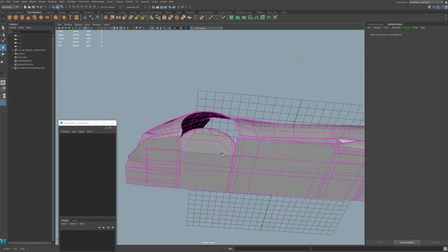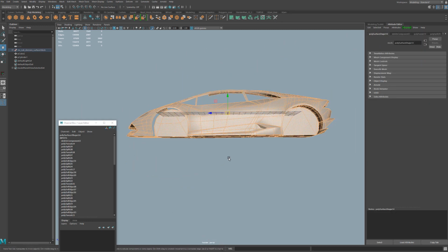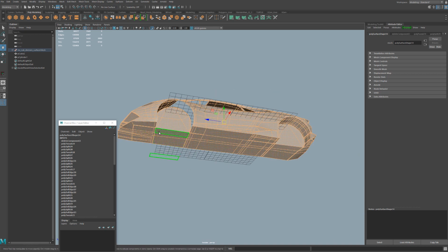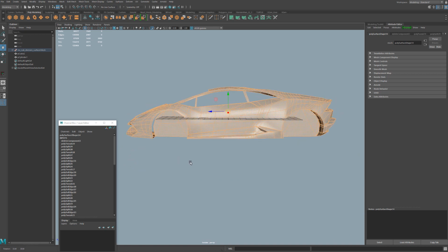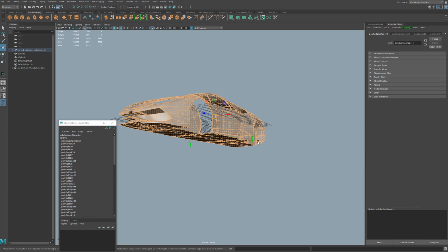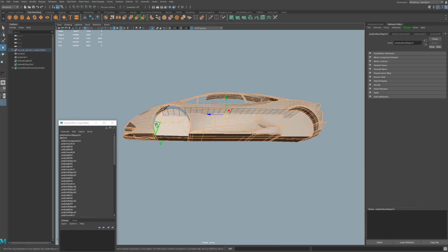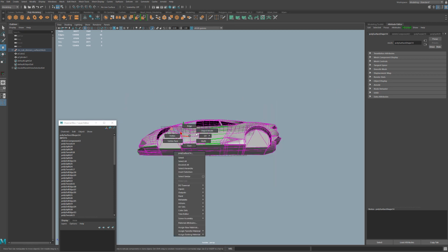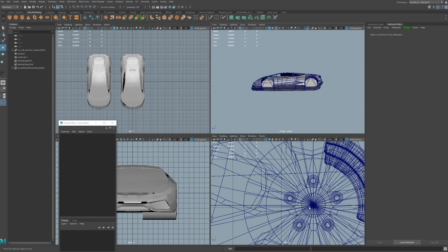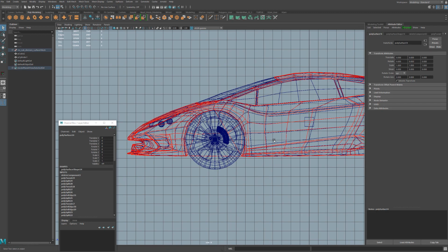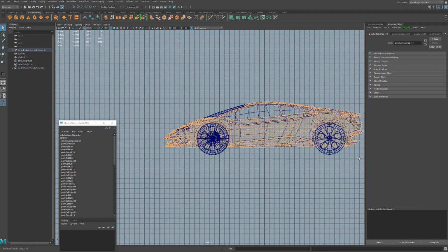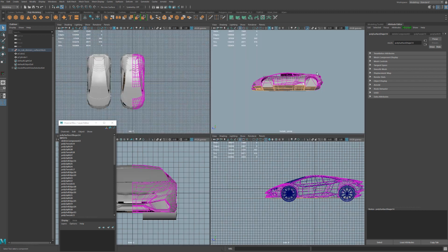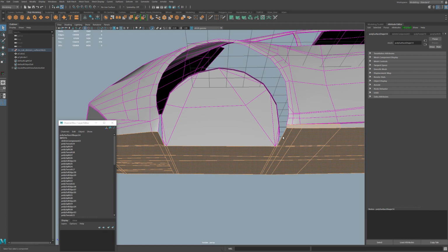When I'm modeling a car, I never have a bottom here until the very end. That's because it's not really going to be part of the body anyway, just this undercarriage part. Usually when you're modeling, you want to have a shell. It makes life easier. So what I'll do here is select this, double click, select my whole mesh, and deselect everything but those very bottom faces.